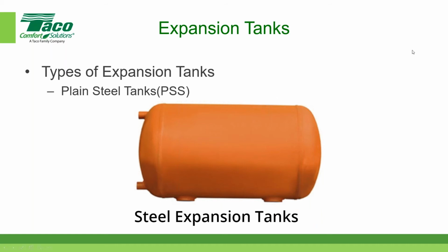Christine's got a pretty good question here. As all questions are, is there a pressure relief as the water level rises? Well, whatever relief valves or systems, those are external to our tanks. So if the design engineer prefers to have some type of relief valve in the system, they would put it as part of the piping. It's not part of the tank itself.